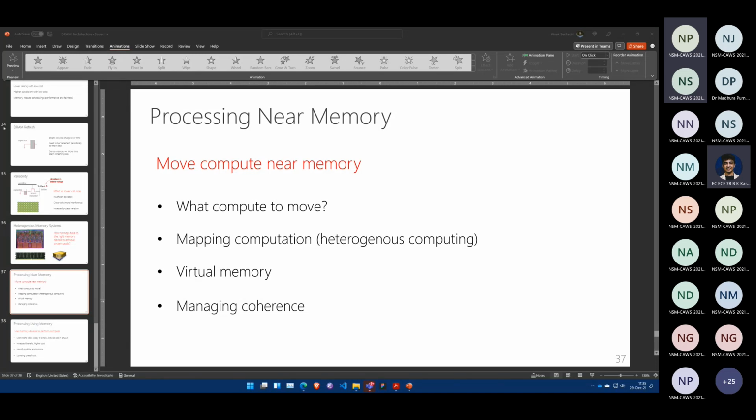The memory controller can fiddle around with those mappings to provide different amounts of parallelism, bandwidth and whatnot. But this has to be done at boot time, so it is a one-time process. At boot time, it determines the mapping that it is going to use to access memory, and it has to use that for the entirety of that particular boot. So the processor doesn't care, basically. It's determined by the memory controller.